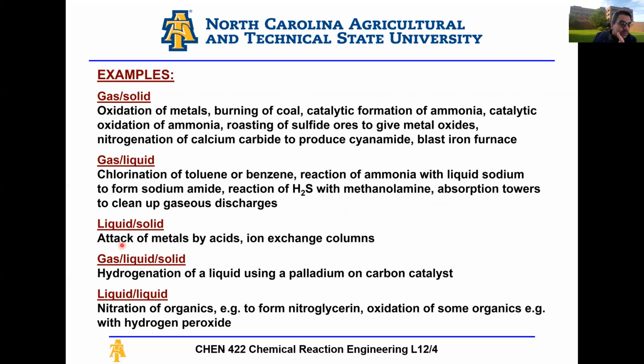Liquid-solids: attack of metals by acids, ion exchange columns. And then you have gas-liquid-solids: hydrogenation of a liquid using a palladium on carbon catalyst. So I have a liquid phase, I bubble hydrogen through it, and I have a palladium catalyst floating in the liquid phase, and I make a hydrogenated liquid. Alternatively, a very common gas-liquid-solid system is the Fischer-Tropsch process, where I bubble hydrogen and carbon monoxide in a continuum of wax, and this wax has iron catalyst or cobalt catalyst.